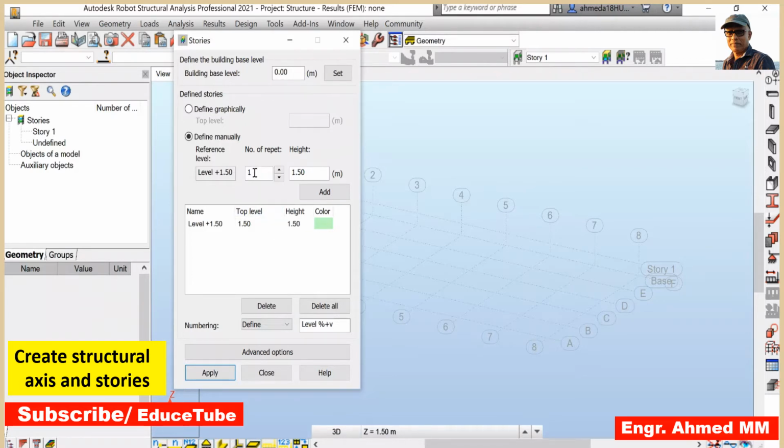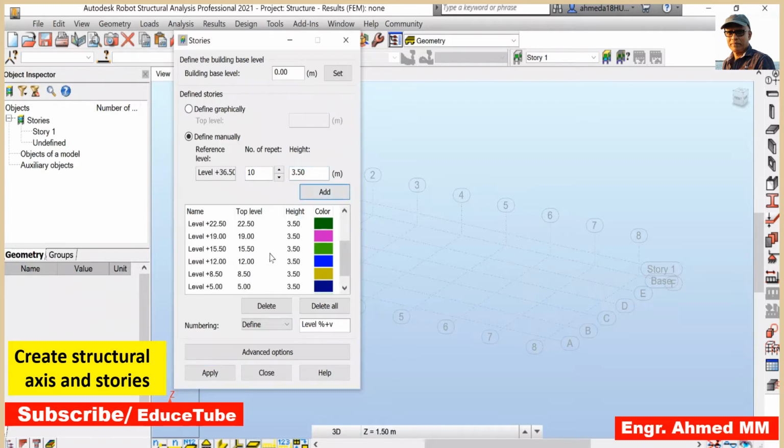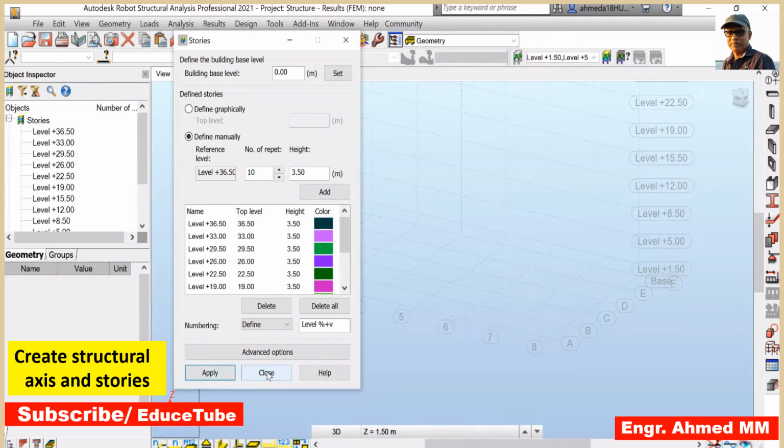Now, see here I am taking 10 because I will create a 10-story building model. So repetition will be 10, but floor height will be 3.5. So let's add this. I got it. So total will be 36.50. So it's perfect. Now apply it. It is done.